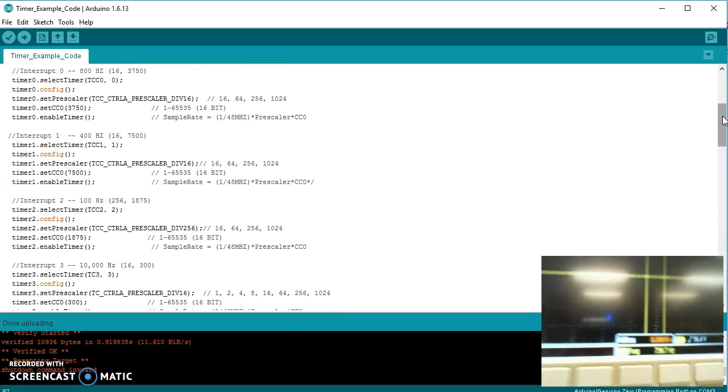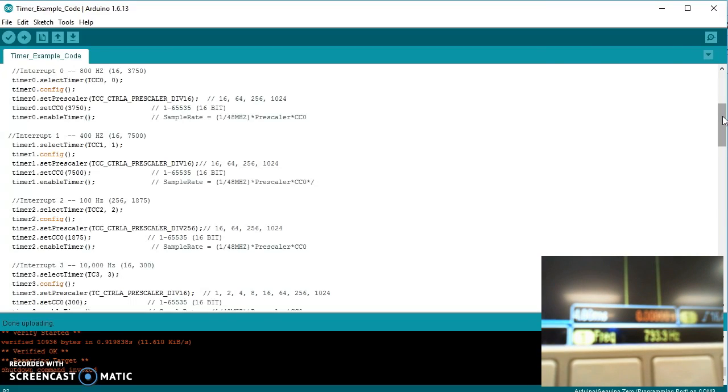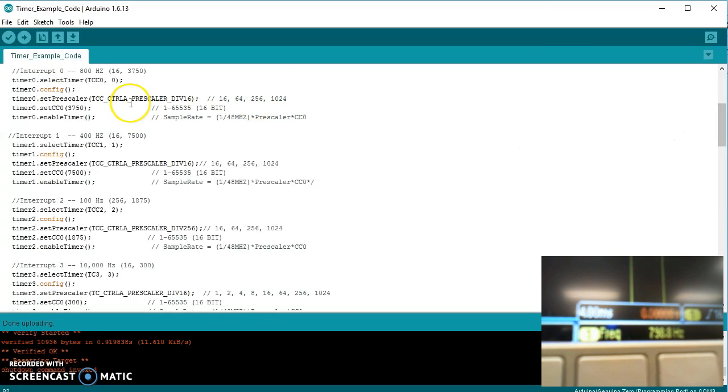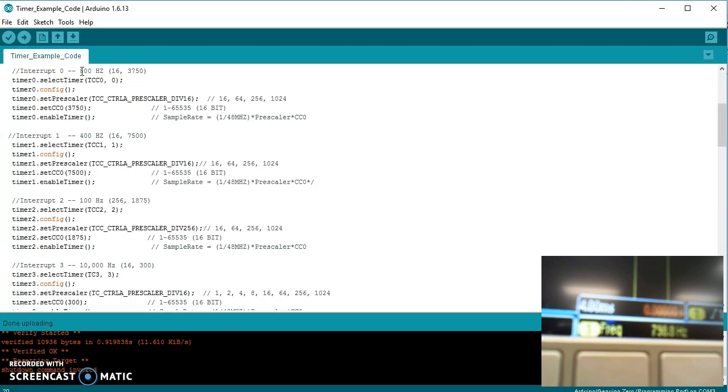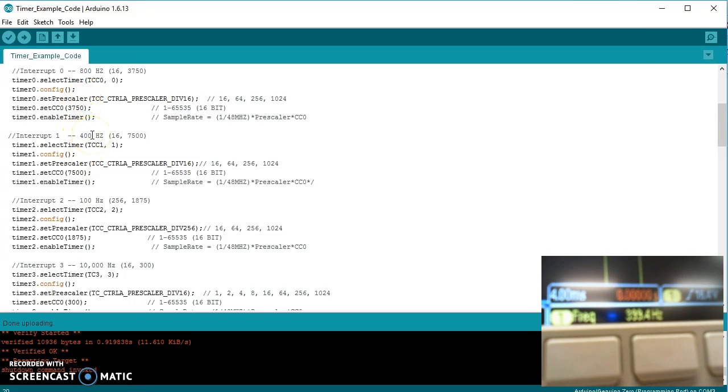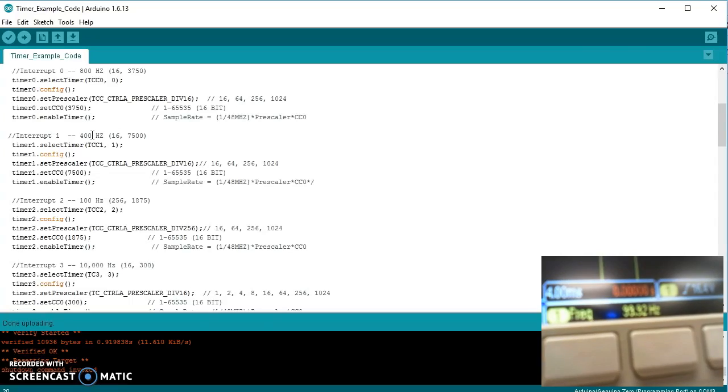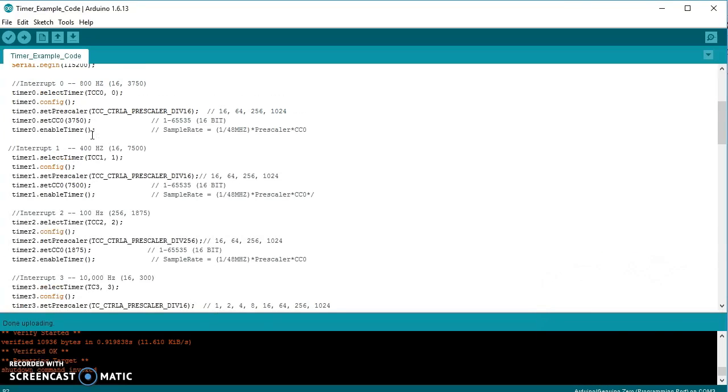you can see right on the bottom middle there, we're running at 800 Hz, and then if you look at our code, we set it up for 800 Hz. And if I go ahead and move the pin 1 down, we get 400 Hz, which is exactly what we want. If we move it down 1 more, we get 100 Hz. As you can see, this is how you test your outputs using an oscope, and it works really smoothly.